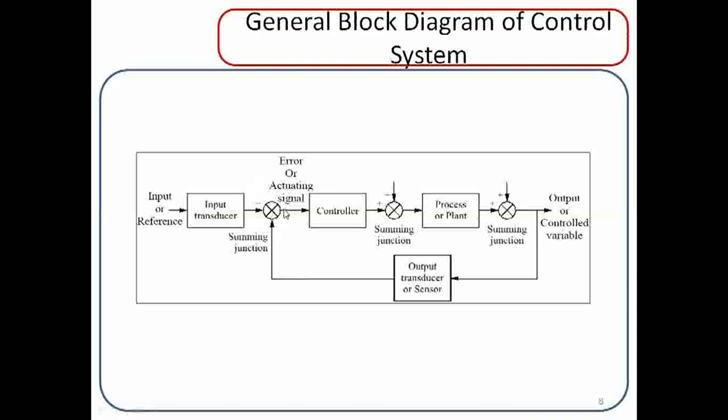For example, you need to get the breadth as 2.6, and the length and depth have been satisfied as per the input or reference values, so we only have to monitor that particular breadth. Depending upon the breadth, how much it has to be progressed: we have got an error of 0.02 mm, and that needs to be compensated, and only that particular set of instructions will be highlighted with the help of this controller.